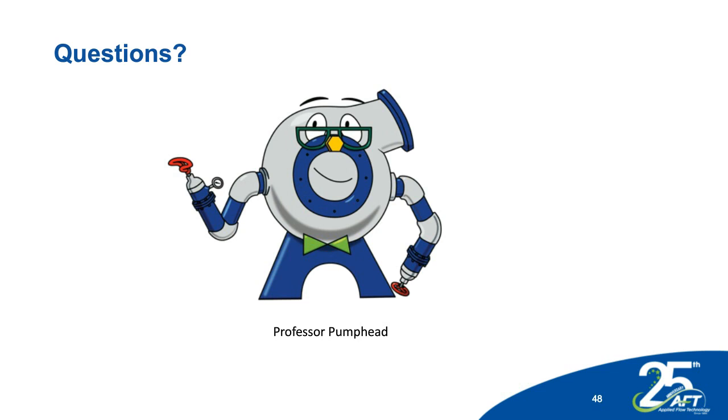Can AFT Impulse model transients caused by positive displacement pumps? Yes, Impulse can model both centrifugal and positive displacement pumps. Something we didn't talk about today, but there's an add-on module, maybe for a different webinar sometime, that can evaluate the natural frequencies that are excited in your piping system from a PD pump, so that you can understand those acoustic frequencies to be careful to avoid those or design for those. And so the answer is yes on multiple levels on PD pumps. That's a really sophisticated feature, isn't it?